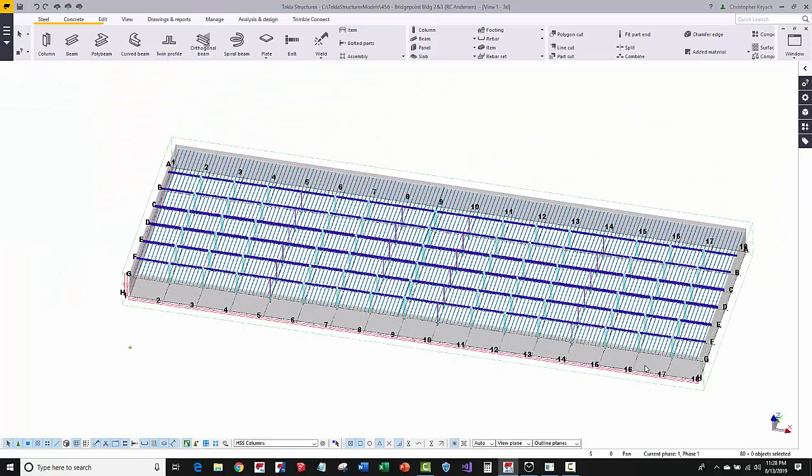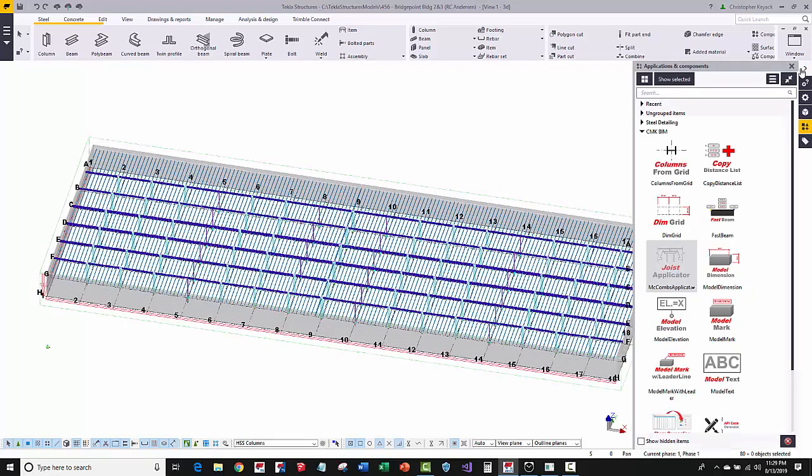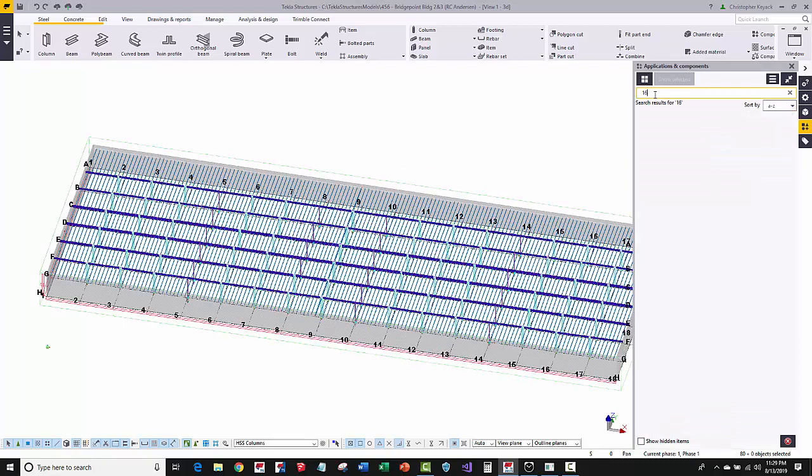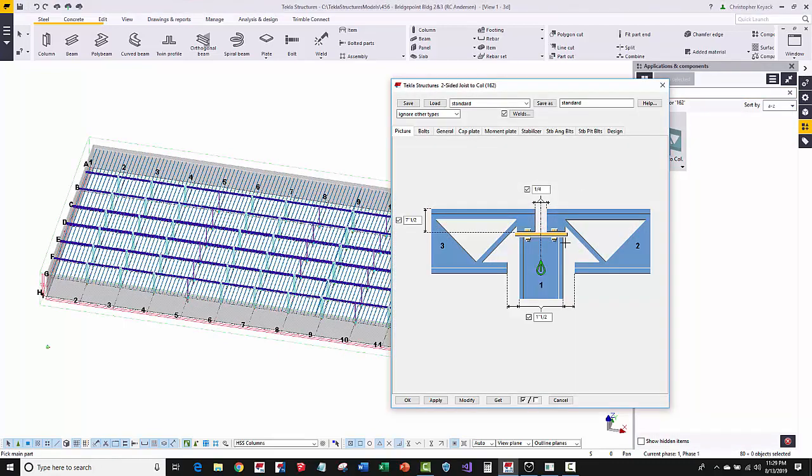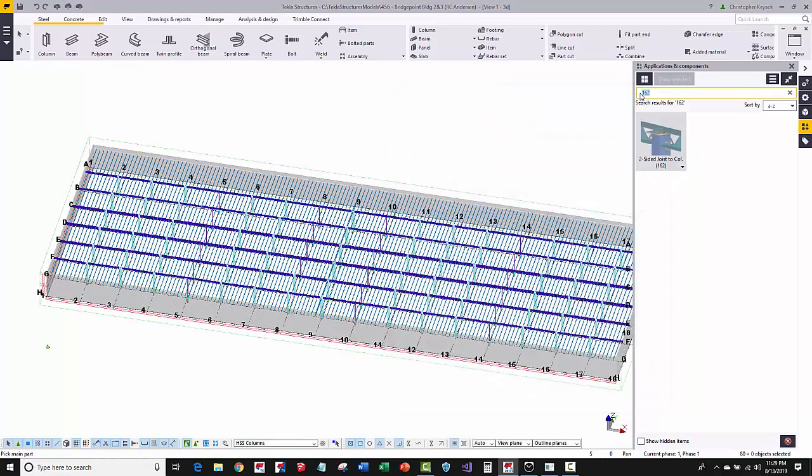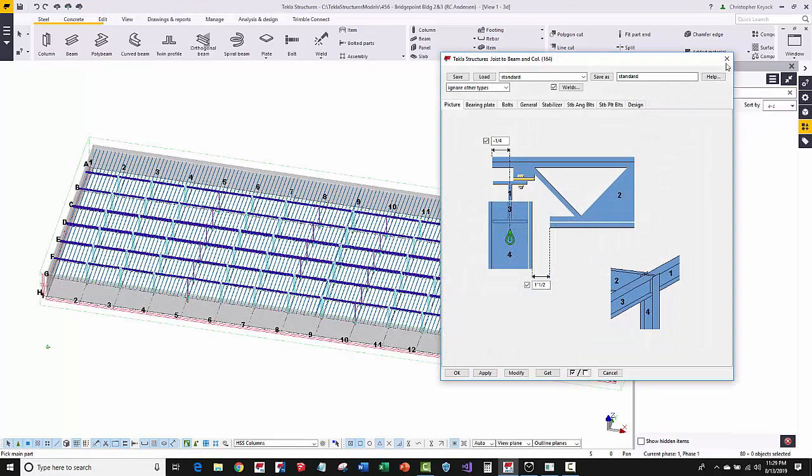columns. Now I've got 80 HSS columns selected. There is a quarter on 12 roof slope all over, and so just trying to copy connections from one bay to the other and one column to the other doesn't always work, and sometimes you'll have to manually apply each of those connections on the columns, which, if you've ever seen 162 and 164, so if we come in here, 162, there's actually quite a few different kinds of picking of the primary and secondaries, and then on 164 you have to pick these, and you have to pick them in a very specific order.